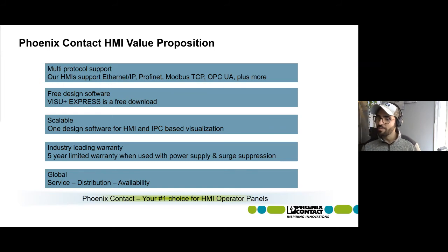Does Visionplus have any conversion tools for other HMI software packages? Direct conversion depends on what you're really trying to do. If you want to take another company's screen and replicate it directly on ours, we wouldn't really have a direct conversion tool. However, if you were importing tags or variables from another PLC, we do have the capability to import them into our software. Whether it be an L5K file or something along those lines, you can do that within Visionplus.